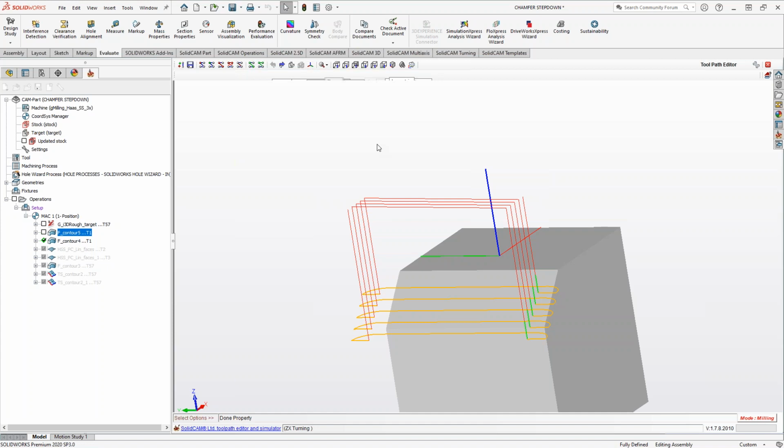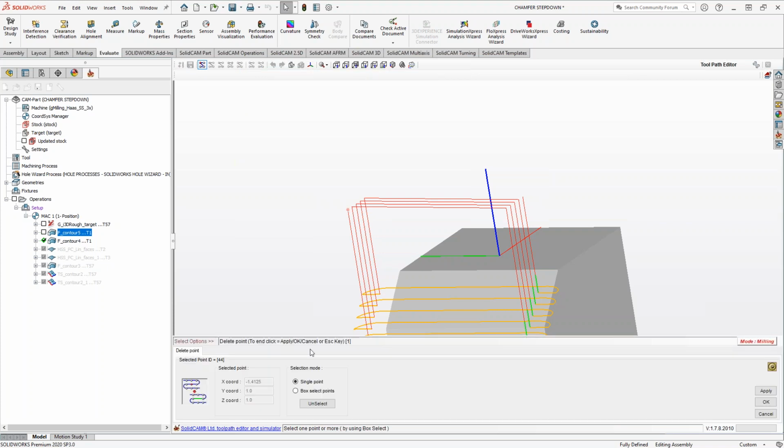But there is a box selection of points in some of these options as well. You'll notice it when I click on some of these. Let's say if I grab that one, there is a box select. So I can grab all those points and then delete all those points as well. So you can do a box select around a hole or a bad translated surface area, and then you can just delete those data points, and as you see, it'll just recalculate to do direct movements between those.